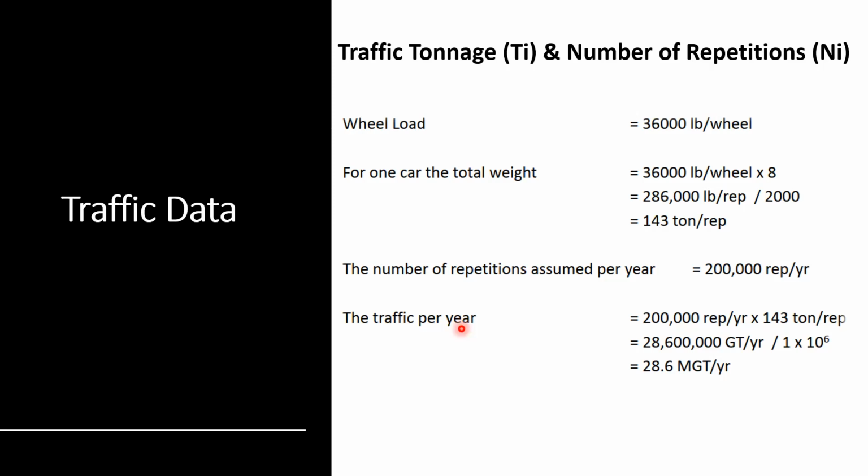Very important parameter, and it's very important because it helps you classify how critical the railway embankment you're dealing with. Usually up to 5 MGT, million gross ton, is considered a light application track. Above 5 is considered one of the more critical or heavy track applications.